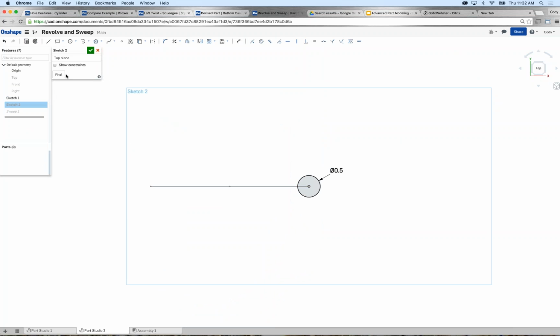If I did not constrain this with a pierce constraint like I did, if I change the first path sketch, the dimension does not update. But if I constrain it like I did here, it automatically updates. So yes, you can dimension it, but it's not the best technique. And the reason is it will not update if you change the sketch entity, if you change the initial sketch. Okay.